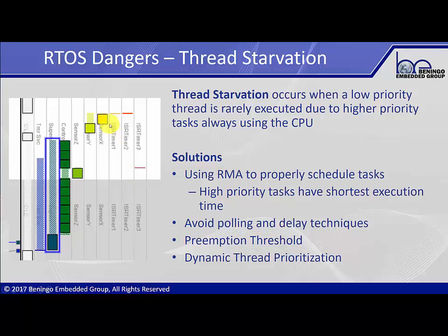You can see here the priorities actually go from left being low priority to higher priority on the right. You can see here we have some ISRs firing, a couple of different sensor tasks that are being executed. You can see here this is the time that the task is actually executing. And these hashed mark lines here show that, hey, this task is actually ready to execute, but it doesn't start executing until right here.